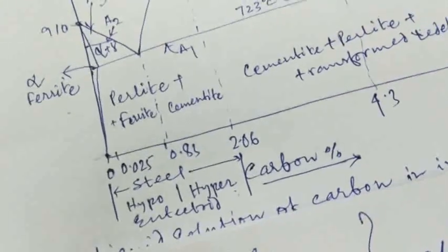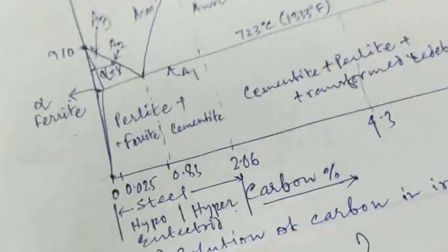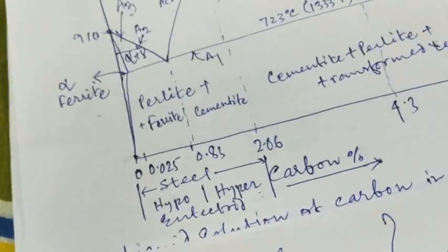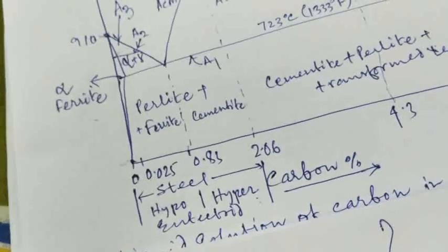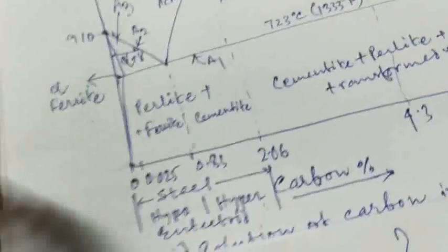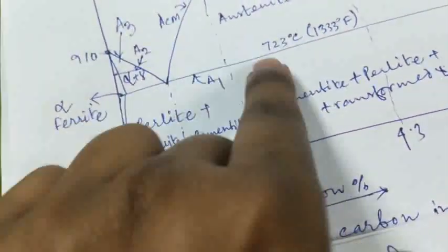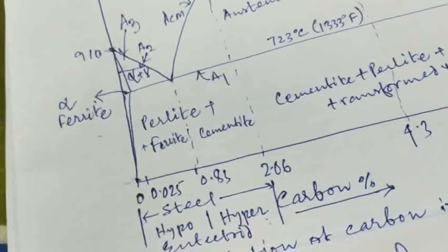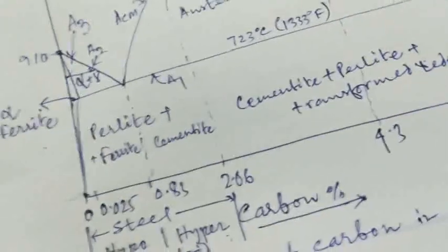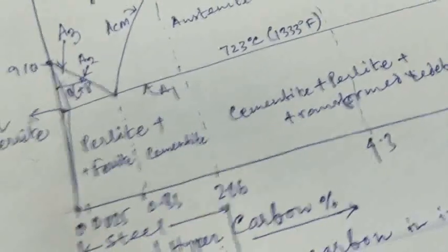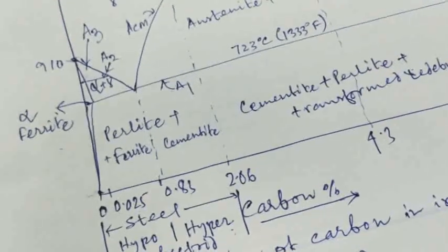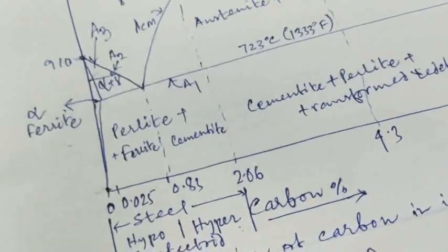Next, spheroidizing annealing. A heat treatment process for spheroidization of carbide in steel to obtain granular pearlite. The steel is heated to a temperature 20 to 30 degrees higher than the A1 line, above 723 degrees centigrade. Holding time should not be too long, generally 2 to 4 hours, usually followed by furnace cooling or isothermal holding at about 20 degrees centigrade below A1 for a long time.